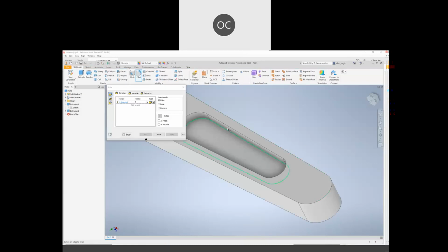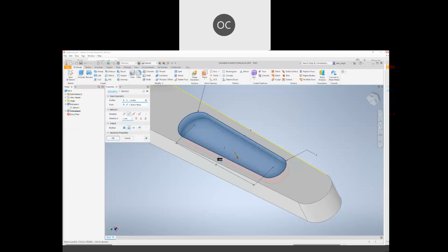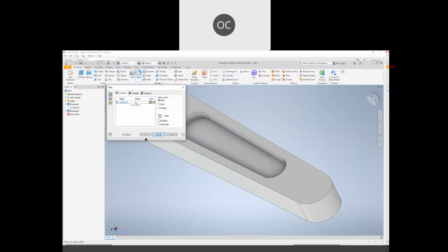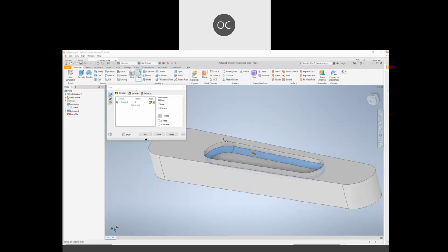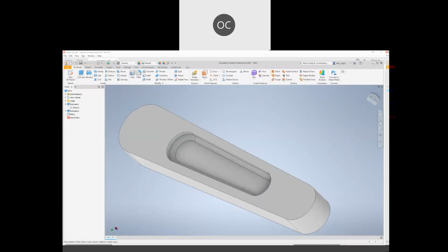So this one, extrude to 2. Just now I stopped my recording actually. So edit features here will be extrude. Okay, cut to 2 and then you click OK. Right, after that will be fillet. Change the radius to 1. Then you select your edge here, which will be the inner edge. So it should look like this. That will be the fillet here. Then click apply please. So ensure that you have this ready to do mirror later.